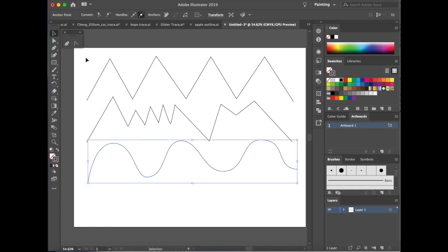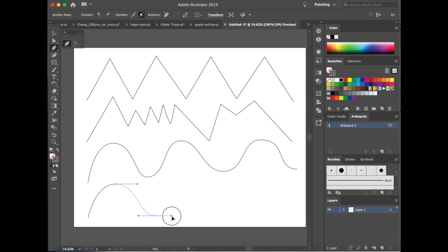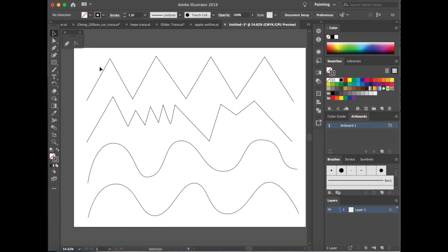Let's do one more. In these videos, make sure that you can do it on your own. Click, click, and drag, and it's just about a quarter of an inch straight in the direction that I'm traveling. So I drag, let go, click, drag, let go, click, drag, let go. The last one can just be a click, then I hit Escape. That's the end of my line. One more thing that I would like to show you, if I want to deselect something, I can go to my selection tool and just click somewhere else to deselect it.